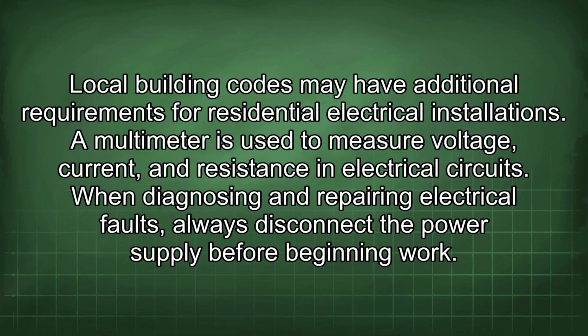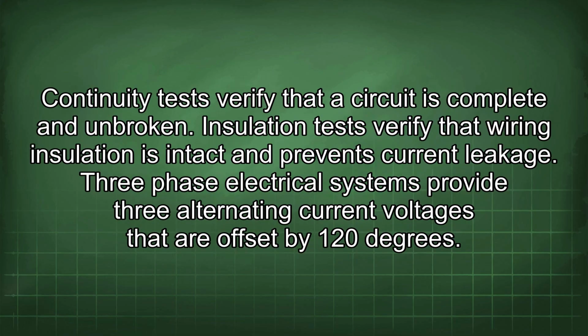A multimeter is used to measure voltage, current, and resistance in electrical circuits. When diagnosing and repairing electrical faults, always disconnect the power supply before beginning work. Continuity tests verify that the circuit is complete and unbroken. Insulation tests verify that wiring insulation is intact and prevents current leakage.